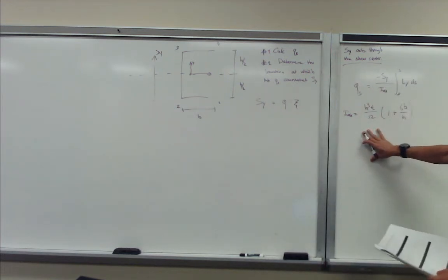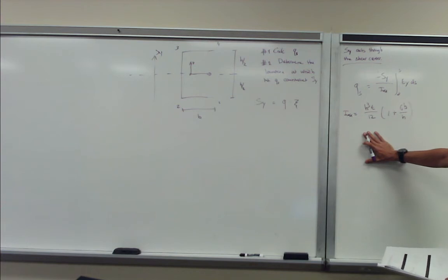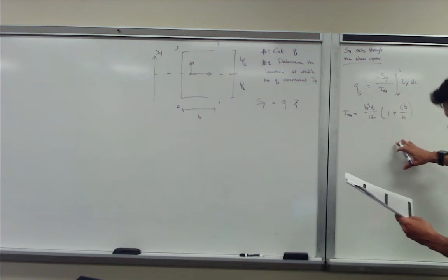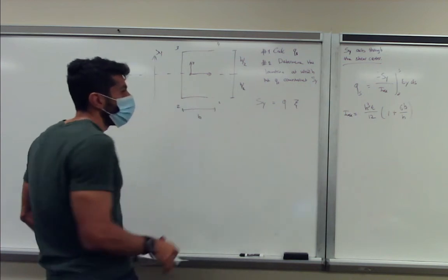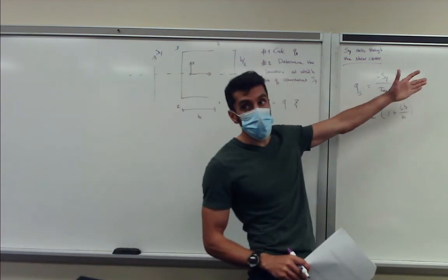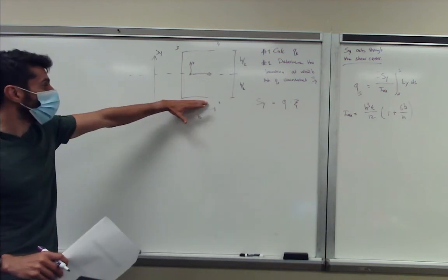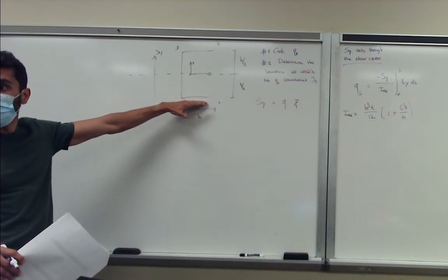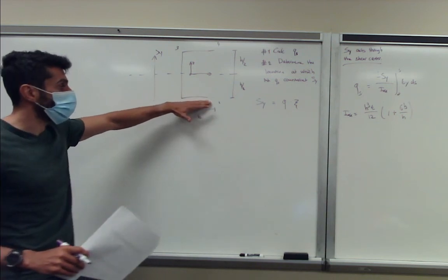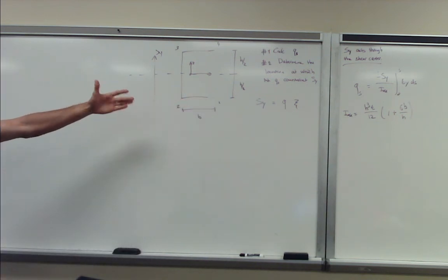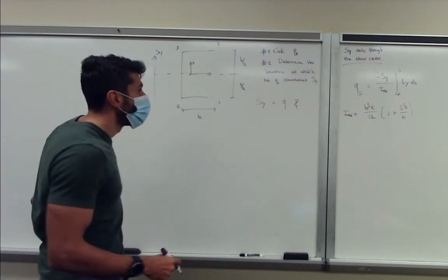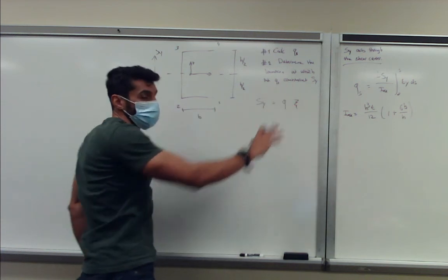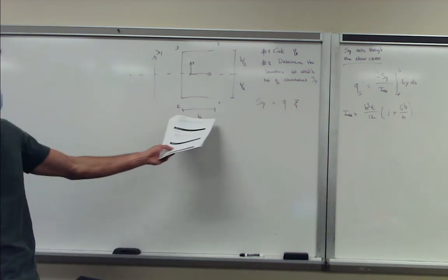So the moment of inertia is h cubed t over 12 multiplied by (1 plus 6b over h), and we just plug this in. Again, in this case there's no x coordinate, so we just have the y coordinate. What's the coordinate of y and how does it vary in segments 1, 2? That's relatively straightforward. It's basically a constant equal to the coordinate negative h over 2, and our distance goes from 0 to b, because that's our path traveled.